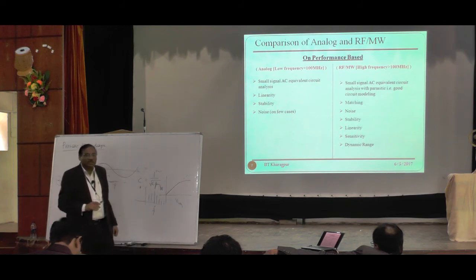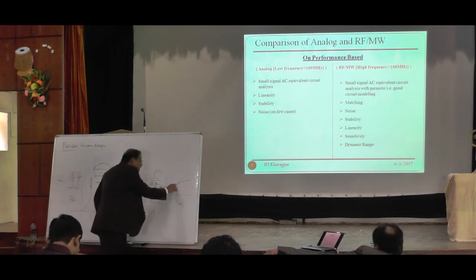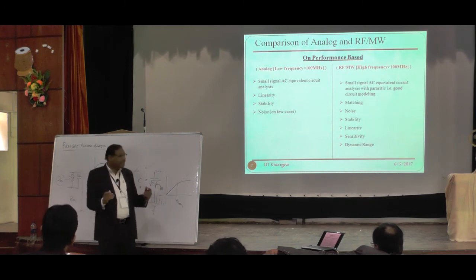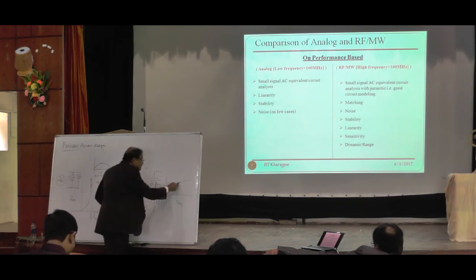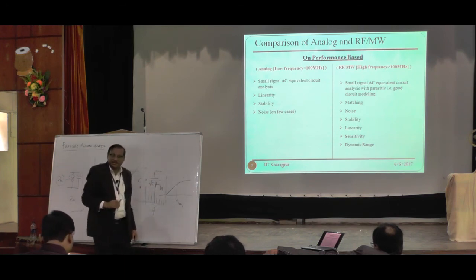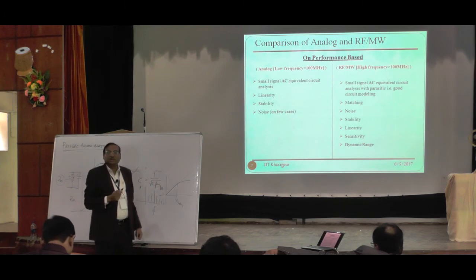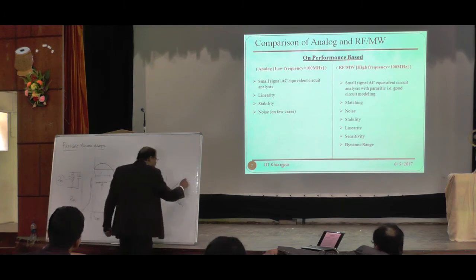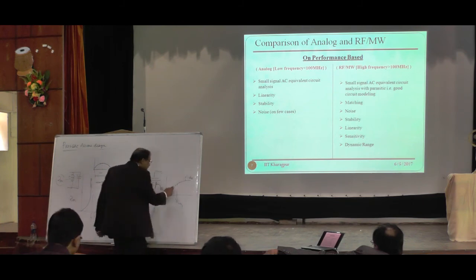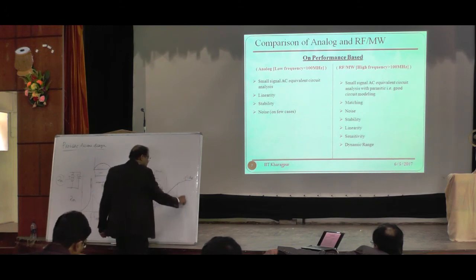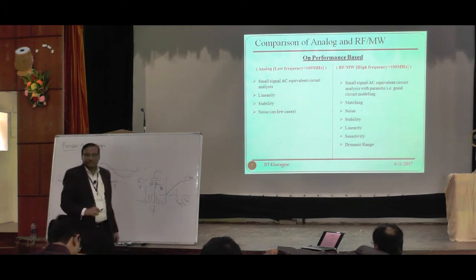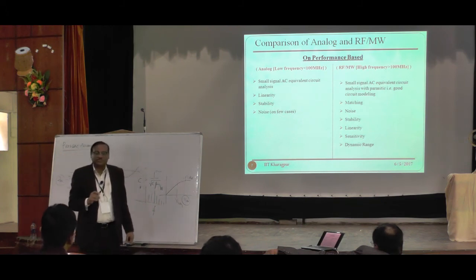That is the nonlinear region. This is the linear region. After that, the nonlinearity part will come, where harmonics are created and energy gets distributed into other harmonics. And we define the input level at which there will be a compression of the expected linear output as the 1 dB compression point. So that is the linearity of the system.